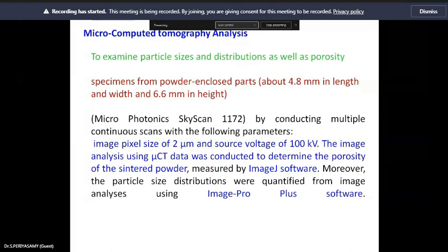Residual stress will be partially relieved after cutting the part from the base plate, causing some deformation. Normally the stress concentration or the internal stress will be relieved by giving a notch or a hole or cutting some portion to relieve it. Here the stress is usually tensile at the top and compressive at the bottom.